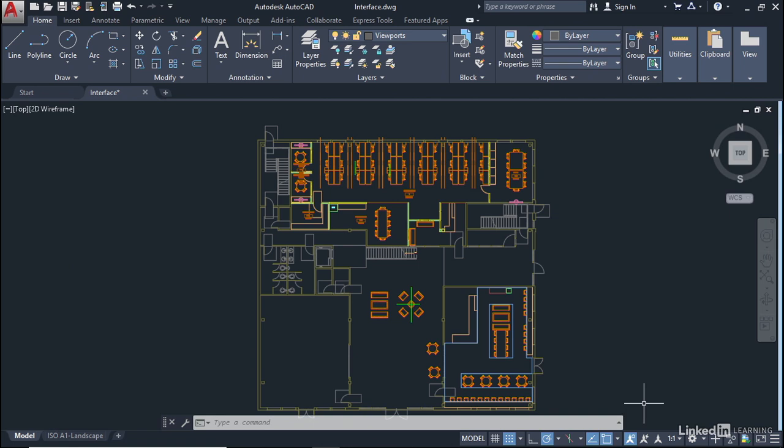So any of those drafting settings that are blue are on. So you'll notice at the moment that my snapped drawing grid is on, my polar tracking's on, my object snap tracking's on, my object snaps are on, and also my annotation objects are showing as always on.